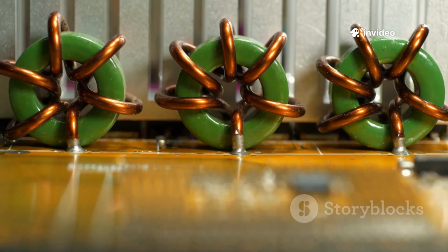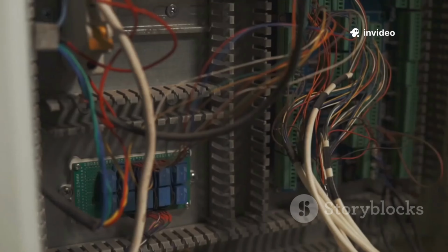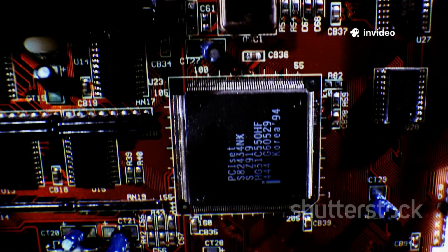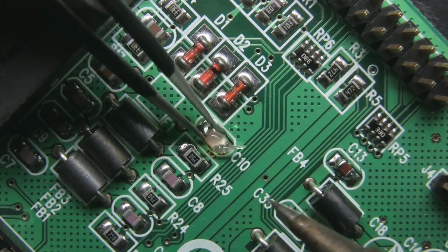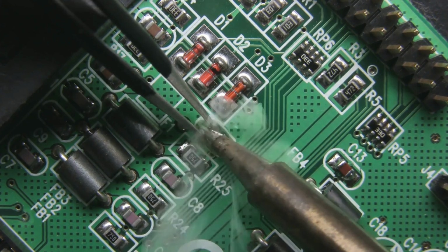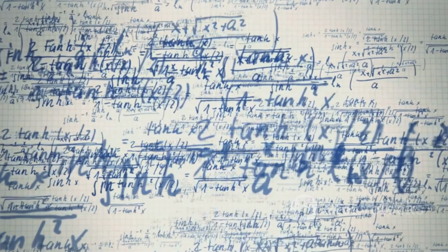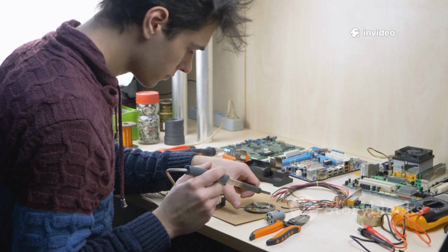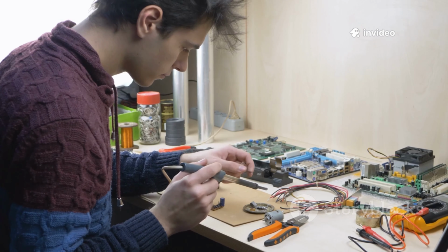Notice 20 ohms is less than either 30 or 60 ohms. That's the magic of parallel circuits. More paths, less resistance. This principle is used everywhere, from home wiring to complex electronics. Remember, always flip your answer at the end. Parallel circuits make current flow easier as you add more branches. Practice this and you'll master parallel resistance in no time.